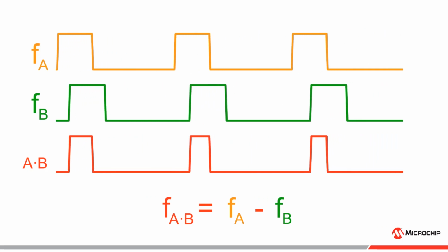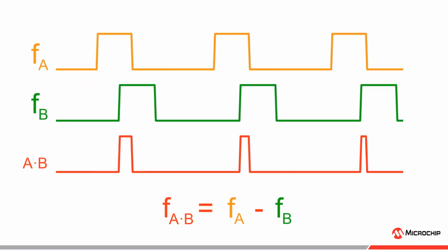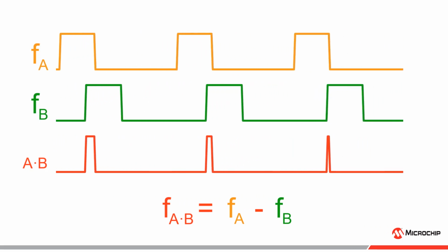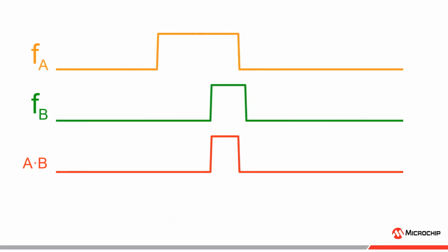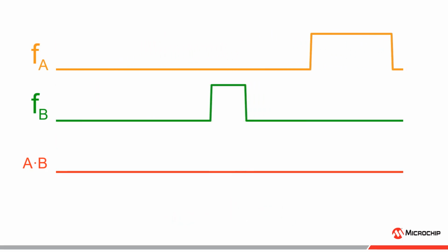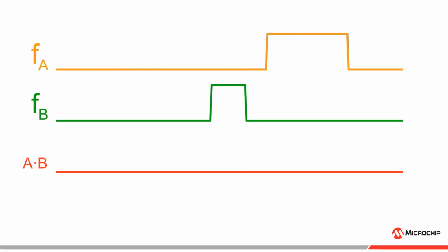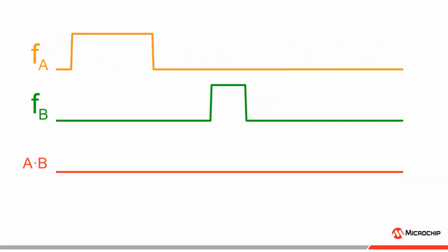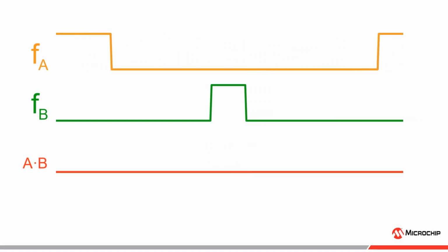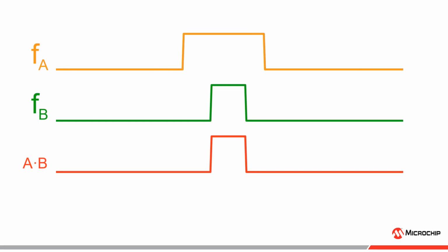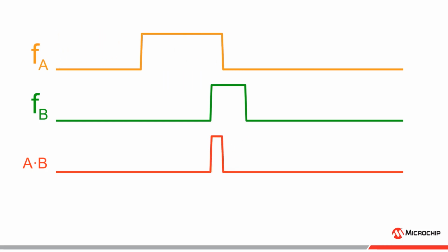This fact can be used to create a pulsating PWM output, where we can control the pulse frequency or period by carefully selecting the frequency of the two input signals. If one of the input signals has a small duty cycle, while the other has a larger duty cycle, then the maximum duty cycle value of the output will be equal to the small duty cycle value. The larger duty cycle will then determine how long the output signal will maintain the maximum duty cycle value before it starts to decrease again and stay at zero for a while.